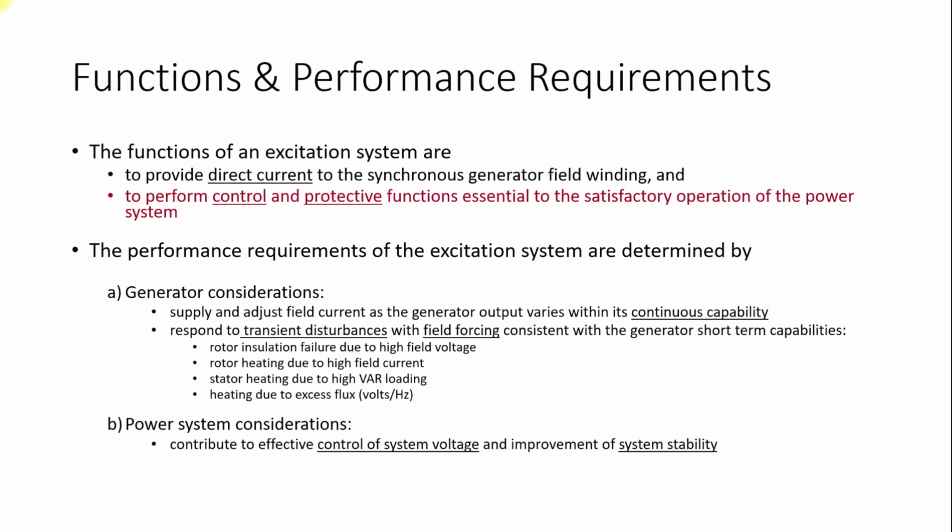You saw in our basic transient stability studies that after post-fault analysis, my generator was continuously oscillating. If P electrical is oscillating, it means that the voltage in the generator will oscillate. When the voltages in the generator oscillate, this can be controlled with the help of the excitation system. Whenever the voltages are oscillating towards the lower side, our excitation system can improve the voltage by increasing its reactive power. Similarly, when the voltages are increasing, the excitation system can perform the reverse action, so it can compensate for the continuously changing voltages.